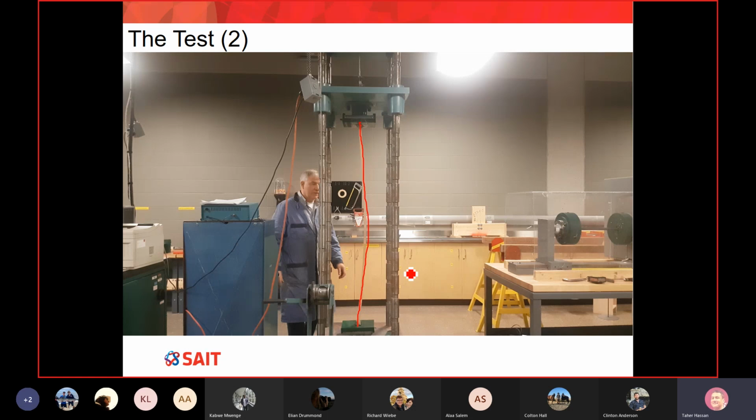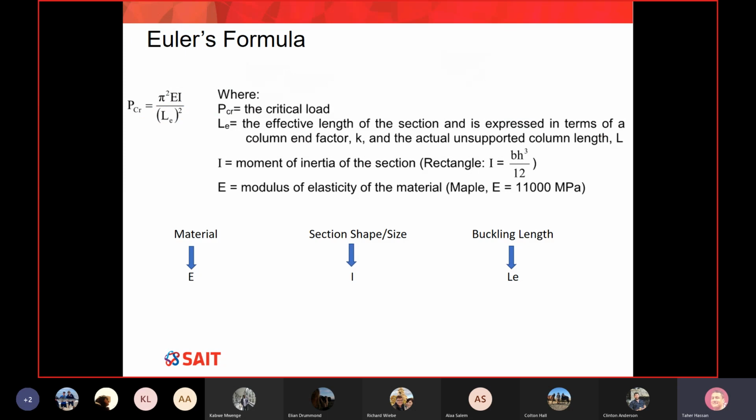Is that something you guys are able to observe? Yeah, we can see it. Okay, so really with those videos, we're trying to show you what buckling means, and hopefully you can see very clearly that my member was pushed out of my straight column before we applied load. So that's one thing. The other thing is we want to show you the end condition. How does it affect the process? It simply changes the deformed wave shape of your column.